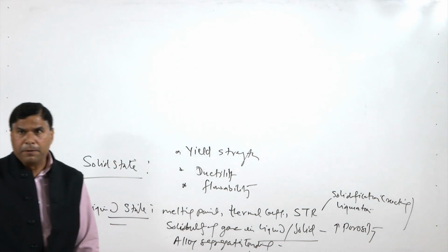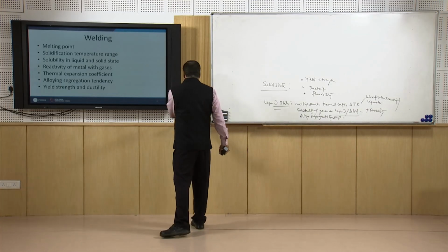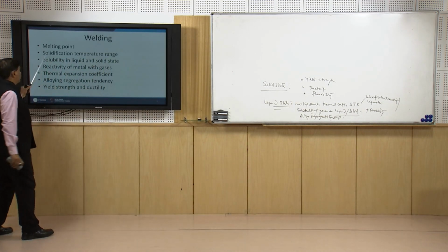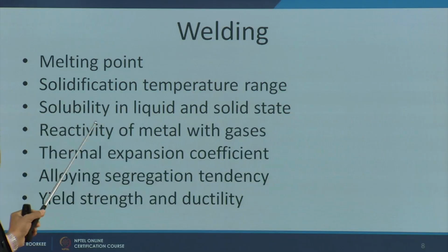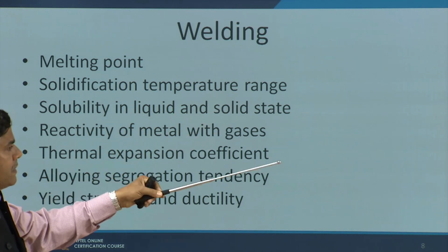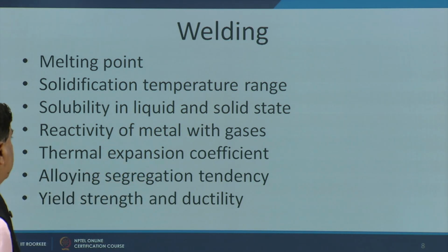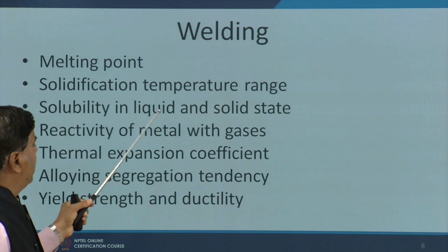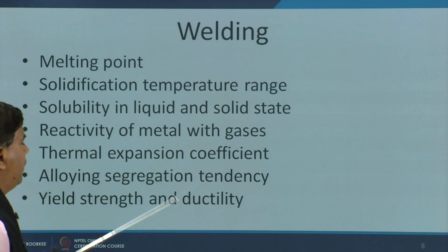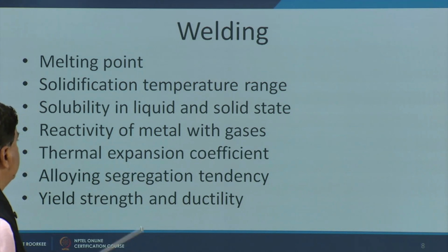So, this is what we have seen in case of welding: the melting point, the solidification temperature range, and solubility in the liquid and solid state. Melting point affects the ease of fusion, solidification temperature range affects the solidification cracking and liquefaction cracking tendency, and solubility of the gases in the liquid and solid state affects the porosity formation tendency.